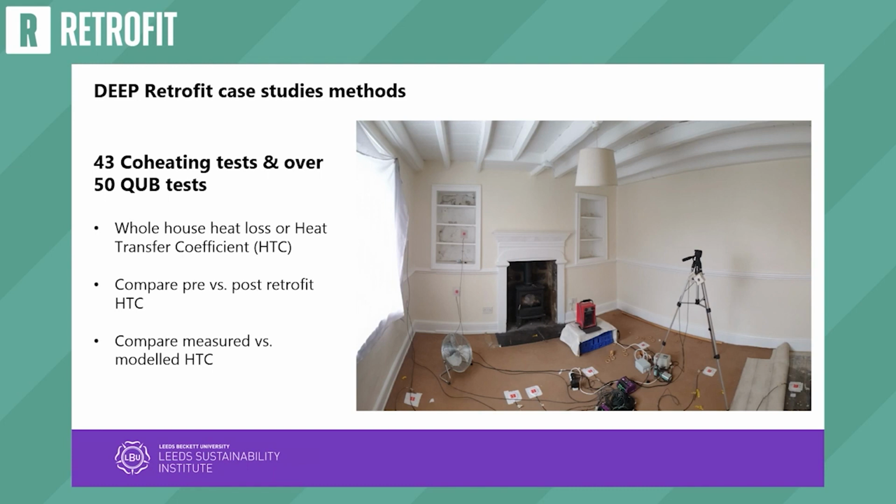We know what all the temperatures are inside and outside the home. We try to create what's called a quasi-steady state environment. We're basically trying to recreate something like a laboratory out in the field. You can't, it's impossible. The wind, the rain, the sun all gets in the way, and that's just life. We've been experts now for the last decade or so at trying to rationalize those impacts on our measurements, to work out how to get rid of them from our analysis, if that makes sense, so that we can pinpoint the measurement of the building and the benefit of the retrofit.